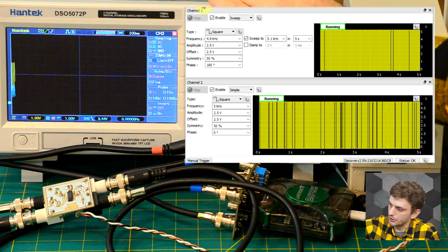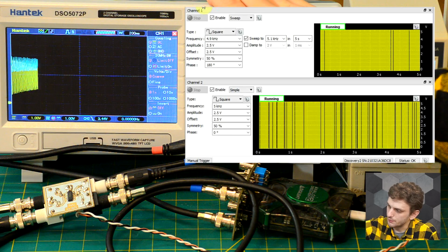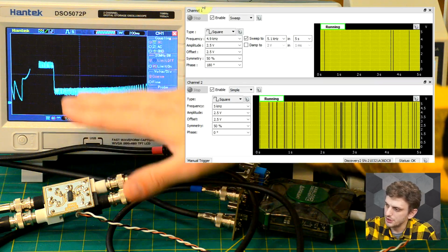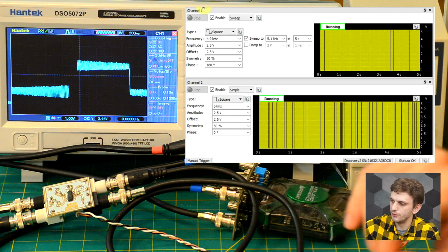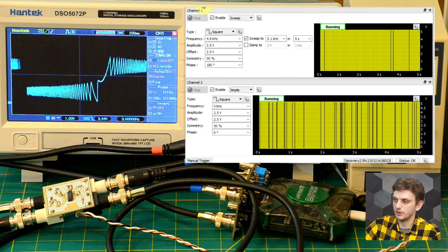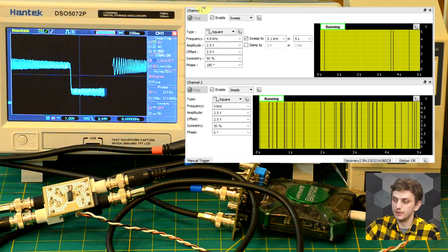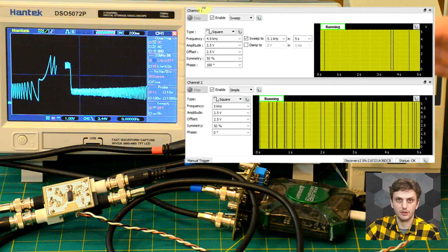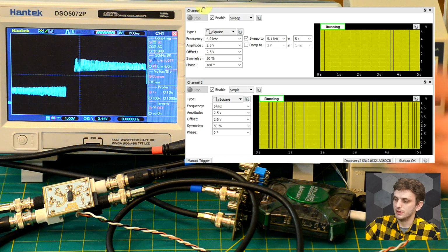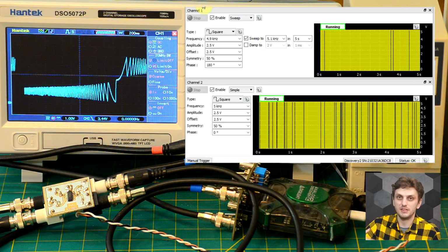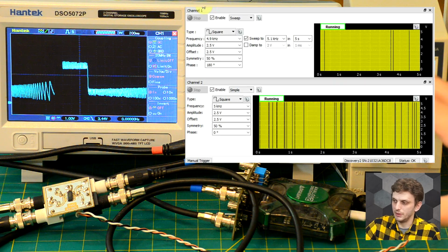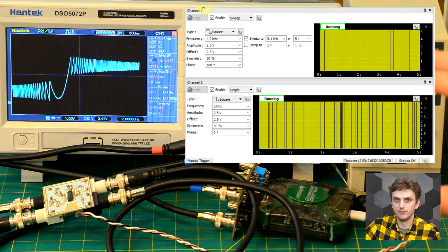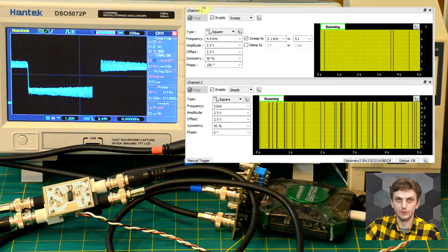On the other hand, if we turn now to the type 2 phase detector, we see that we have two clear regions in which the signal appears, either on the upper half or the lower half. So based on whether the frequency difference is positive or negative, we are in one half or the other of the output. So this is a clear indication of how the phase frequency detector part works. So we have a completely different response depending on what the relationship between the two frequencies is.